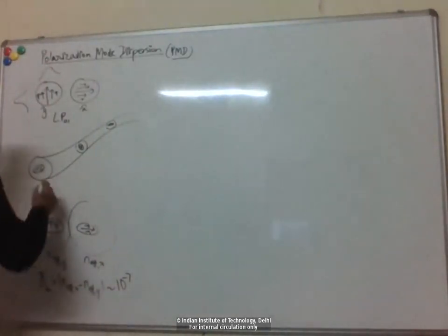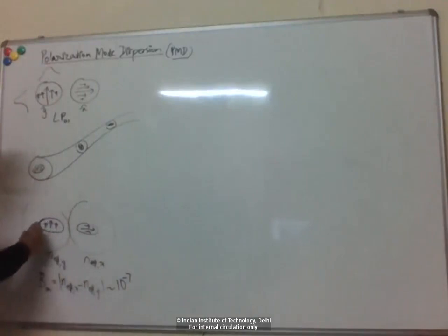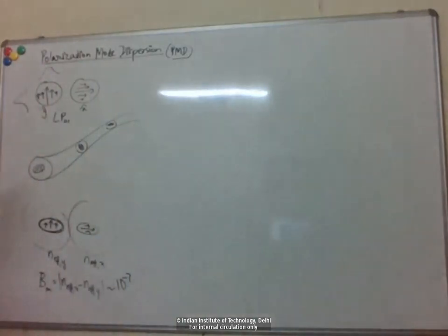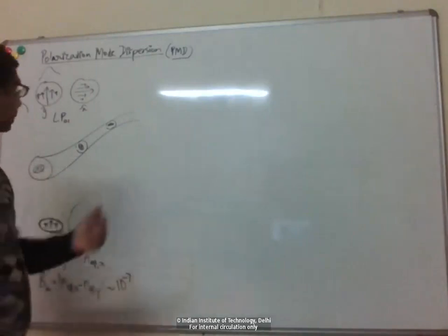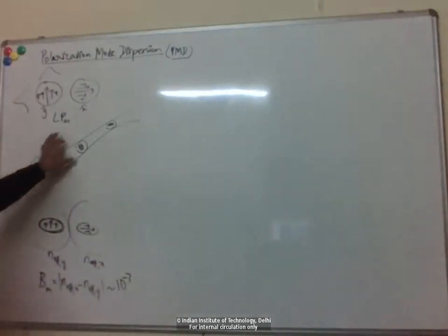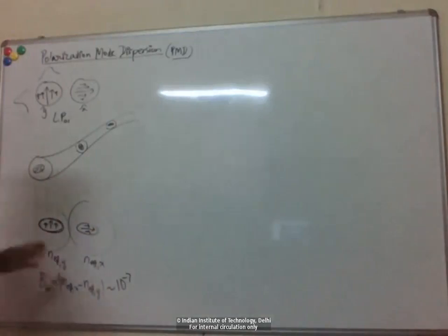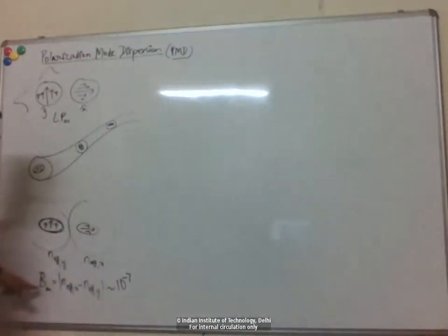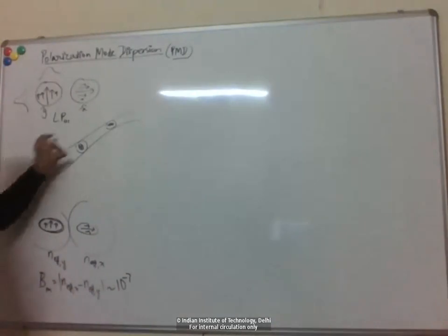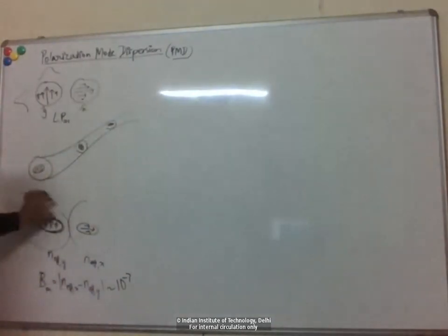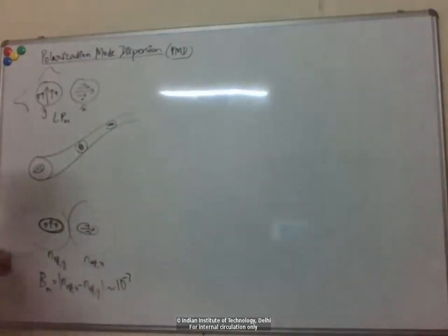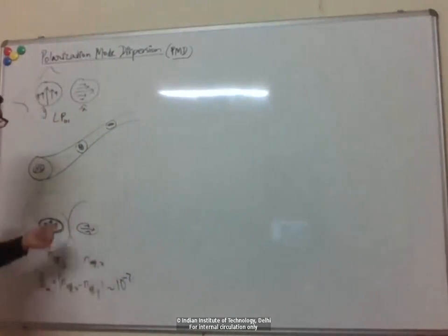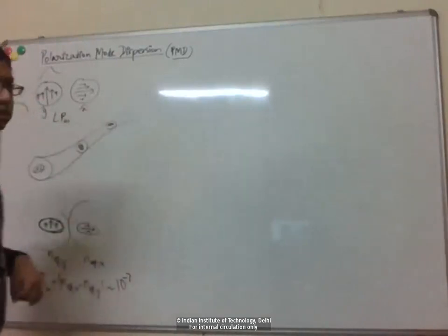So let's first imagine if you had an elliptical core which remained constant over the length, right? So basically, this birefringence is a constant number over the length. In actual practice for optical fibers, if I choose a particular x and y axis, this birefringence is changing with length, right? Because this ellipticity is in different directions along the length. Okay, so basically this birefringence is not a constant, but a random number varying across the length. Okay.